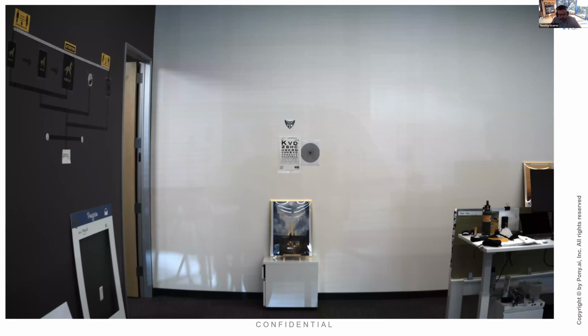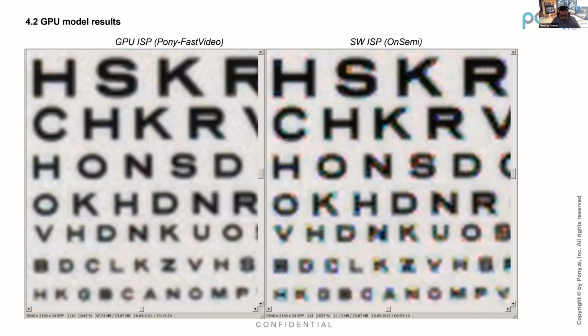So here we were able to reach a better false color suppression and a little sharper. We can see probably one line or maybe even 2 lines more, just because the demosaicing algorithm is superior. So you can increase, for example, the system to 8 mega, and you will reach pretty much the same increase. Or you can apply better demosaicing to your current one. So it all puts together.